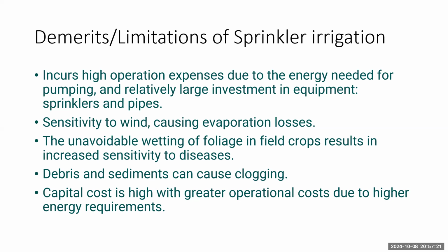If wind speed is higher, in that case, the sprinkling pattern will be disturbed, and the watering will not be done evenly. So that's why it may result in evaporation losses, and watering is also not done evenly if the wind speed is high.